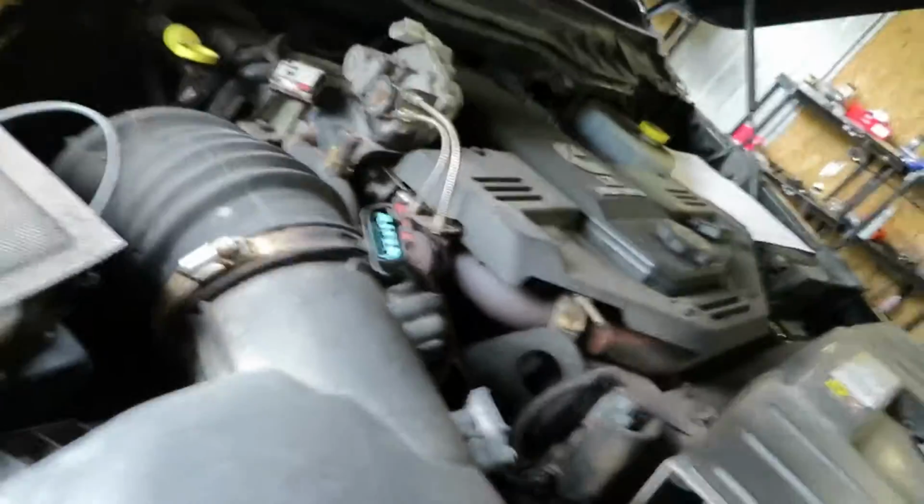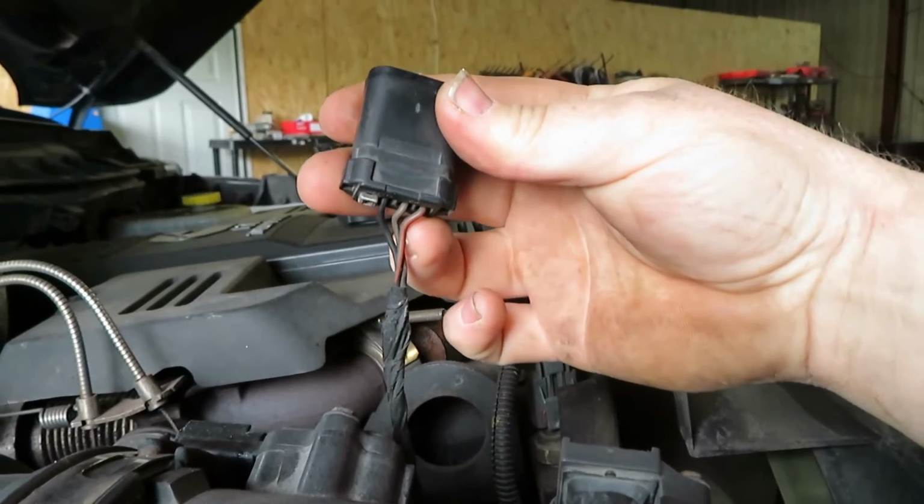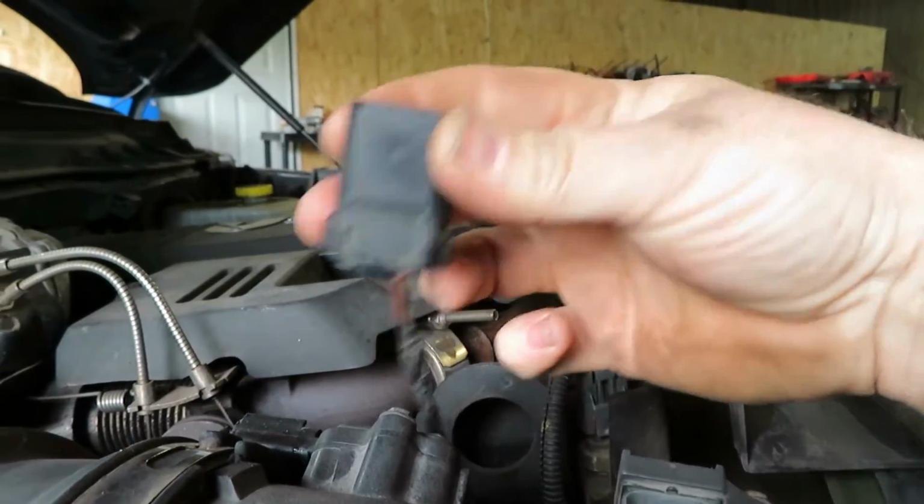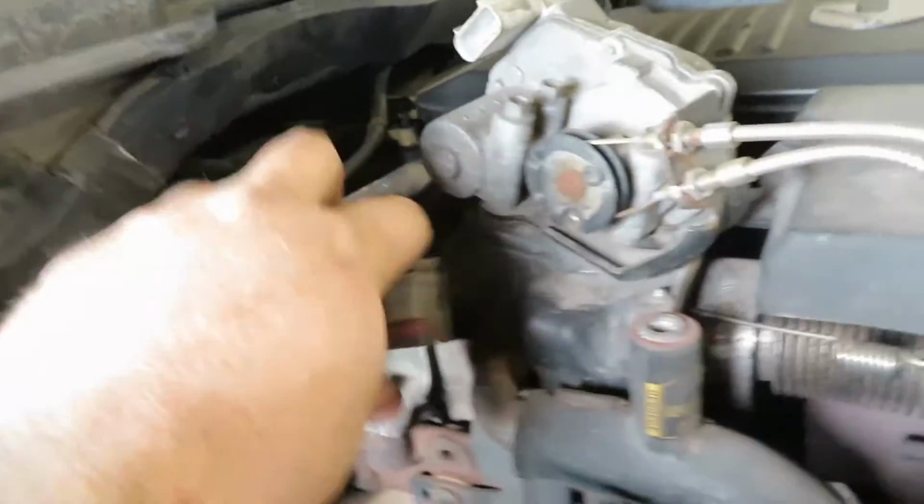So yeah, on our turbo actuator, there's hardly any voltage. On our mass airflow, there's hardly any voltage, and same with the EGR mixing valve. So on the mass airflow, it is this wire here, a brown with an orange tracer, and same with our spool valve. So then what you need to do is find out if the relay is working like it should and sending power to those fuses. Since there's no power there, then the relay isn't getting triggered or is bad.